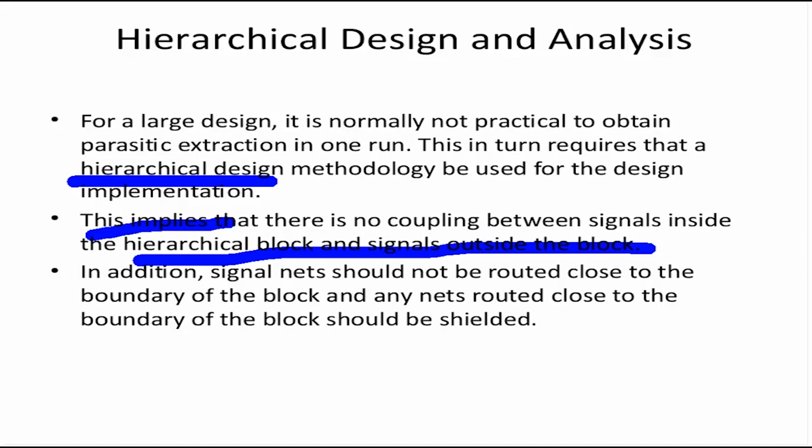Now this memory controller layout, since it's separate, will not have any coupling with USB or CPU, because they are located in a different part of the chip. So this is what it says here: hierarchical analysis implies that there is no coupling between signals inside the hierarchical block and signals outside the block. Now at chip level you can say that all my functional layout blocks are black boxes, and do the coupling analysis only for signals at the top level, right? Many things I said might be confusing here, but when you start working on designs in the industry, you will understand them better.